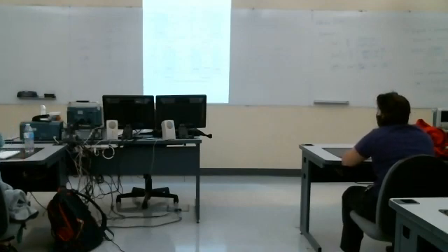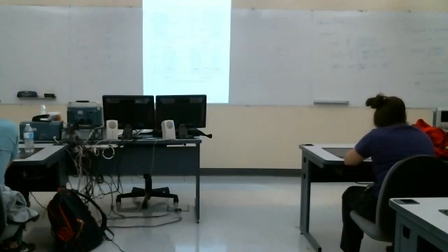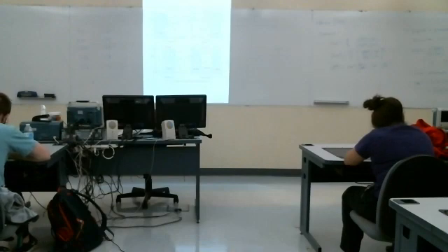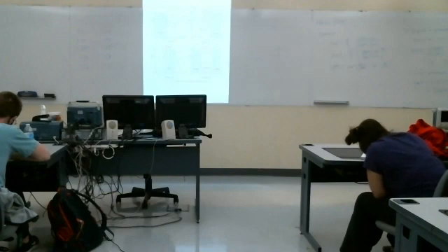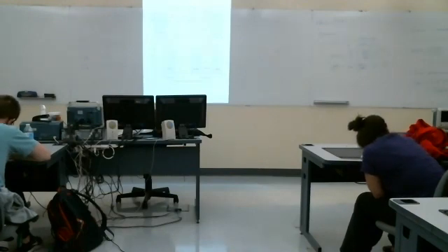So the 20 log of 10 term is just a constant 20. But now we've got two terms that look like this generally, 1 plus j omega over omega c. In one case, omega c is 8,000, and the other case it's 1,000. We're adding the term that's like that in the numerator, subtracting the term that's like that in the denominator.